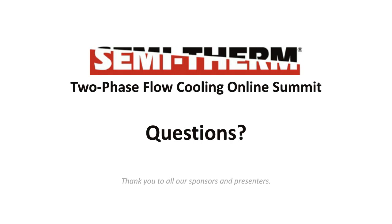Next up, we have, what is your insight on replacing fins with thin metal foam in natural convection applications? Natural convection applications are also a situation where metal foam works quite well. You can really reduce the overall volume of the heat sink. And because the pores are so open, you can get quite a lot of airflow through there, even with natural convection, even if you don't have a fan or forced convection.